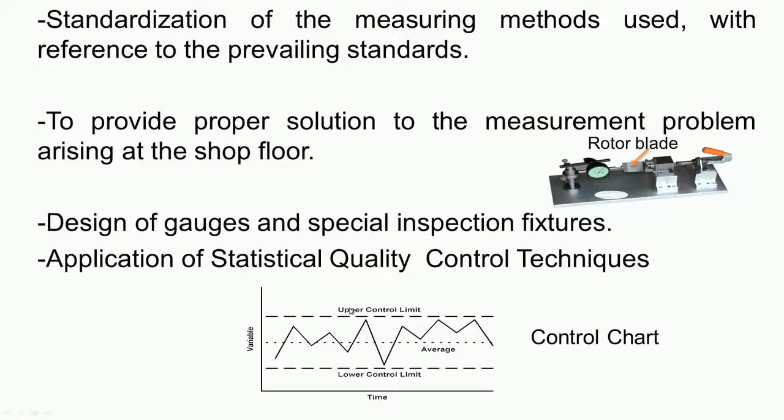And sometimes very complicated components like a rotor blade will have to be inspected. So in such cases we need to devise special inspection fixtures. One such example is shown here. We have the rotor blade which has a very complex shape. So we need to design and fabricate a holding device for holding the rotor blade, and then we have indicators to measure the various